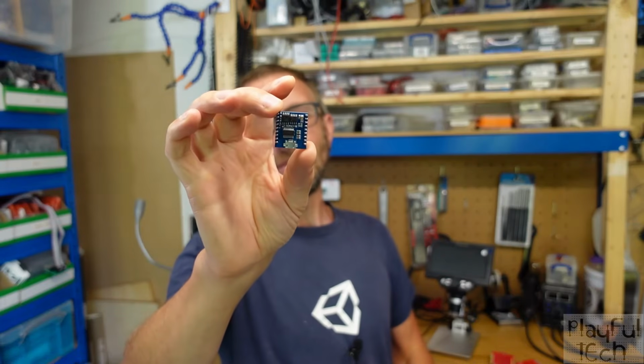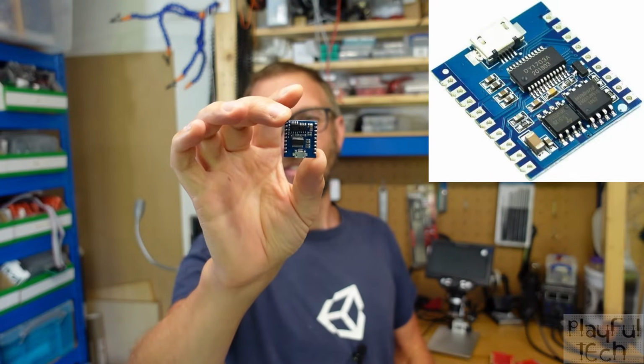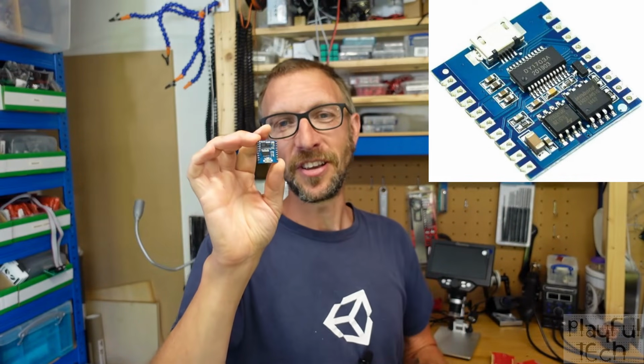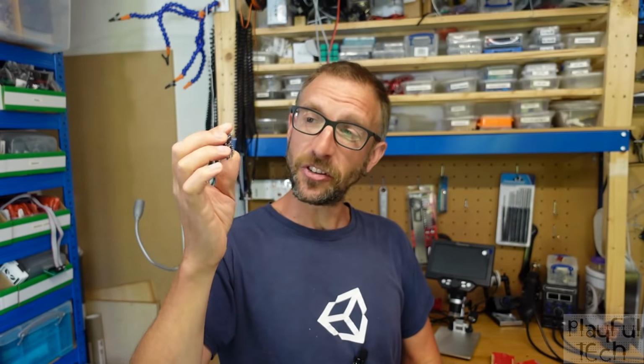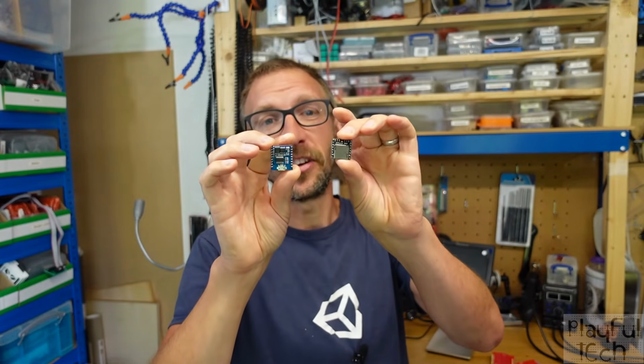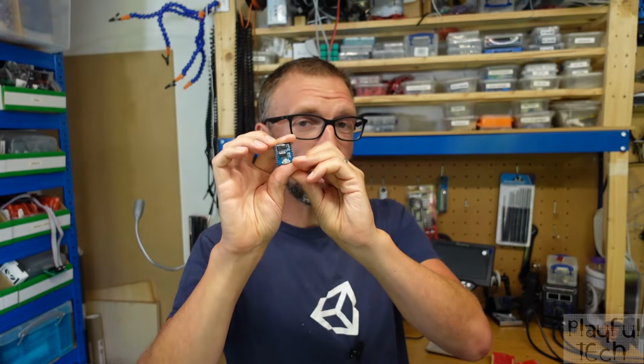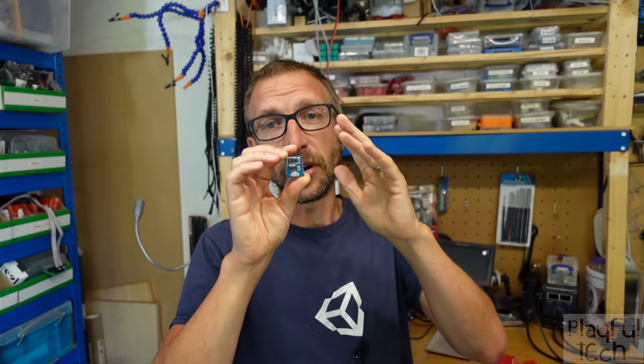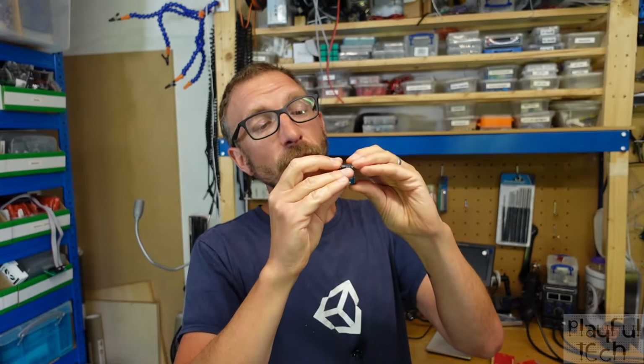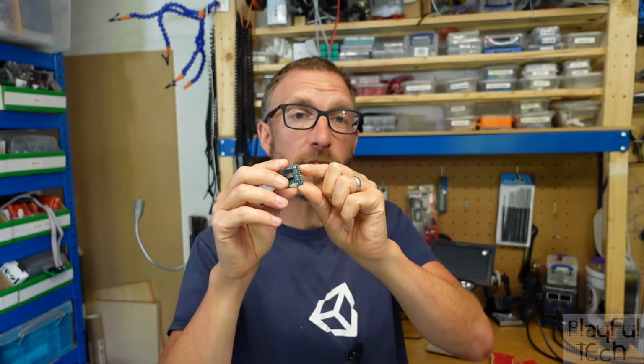This is the DY-SV17F, and it's the most basic board in the DY family. It's a compact module, slightly bigger than the DF player, and like the DF player, it has an audio decoder chip together with an integrated amplifier that can be triggered either by a serial connection or used standalone using the I/O pins on the side of the board. Also, like the DF player, it can provide audio output either via speaker pins or via a DAC output.